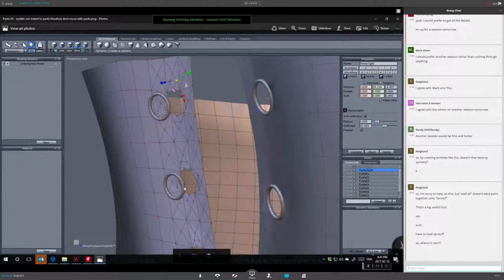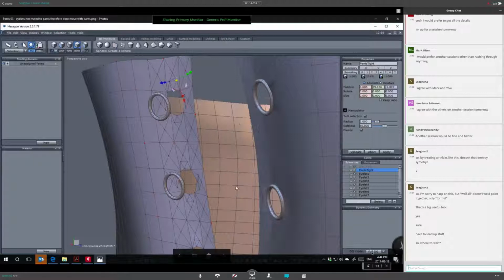The tool below there is one with a chain, and that says group. You press that, and then you will have a group which you can name. You can still open it by clicking on a little arrow beside the group's name, and then you will find all the individual objects below there. And you can also ungroup it again, so you will lose nothing.